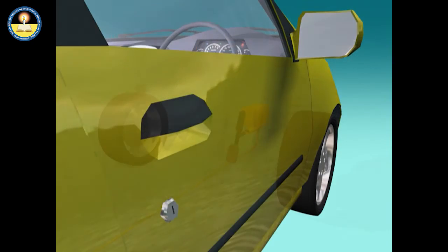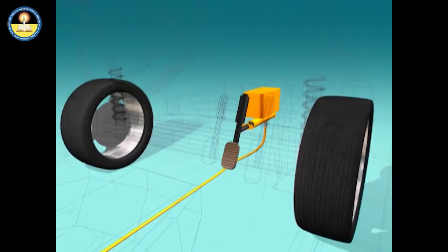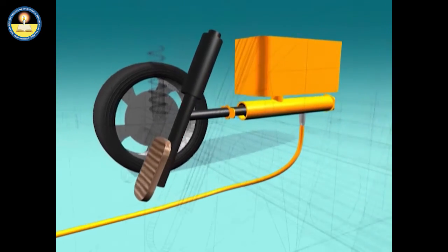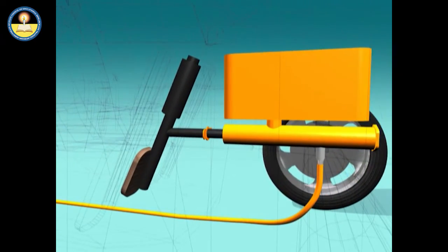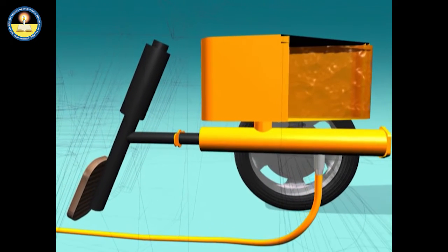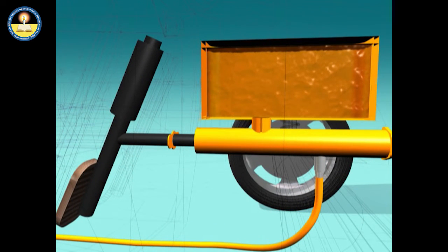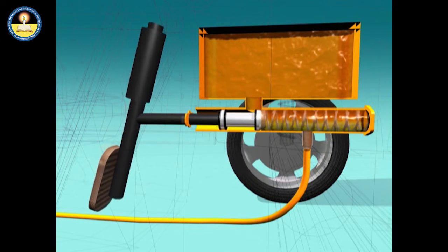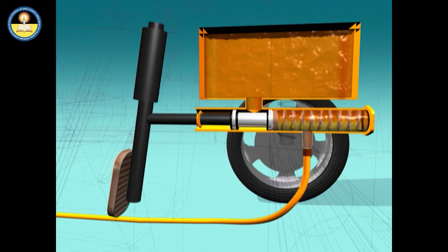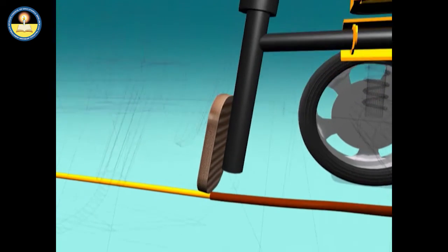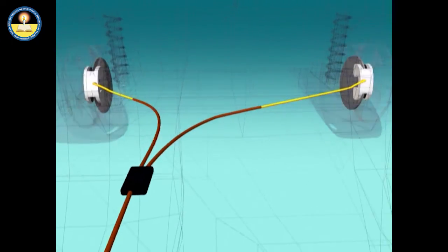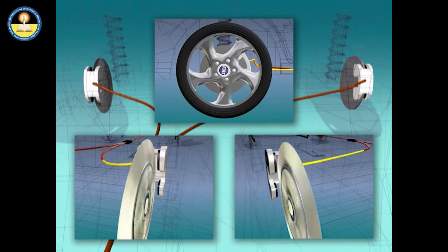An important application of Pascal's law can be seen in hydraulic brakes used in vehicles. Similar to the hydraulic lift, when the driver of the vehicle exerts a smaller force on the brake pedal, it pushes a piston into the master cylinder of the brake, containing brake fluid. The brake fluid from the master cylinder is led through strong pipes to the slave pistons, one at each wheel, and each piston has a larger area of cross-section for brakes.